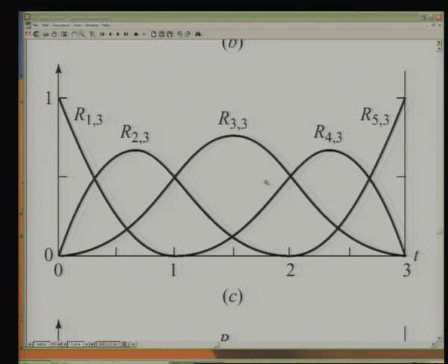So, what you see here, the middle one, what is the significance of the middle one? It is influencing the 3 segments, isn't it? What are those? u equal to 0 to 1, u equal to 1 to 2 and u equal to 2 to 3, whereas if I look at an earlier segment, it is influencing only 2 and this one is influencing only 1. So, this particular function which is influencing the 3 continuously repeats.